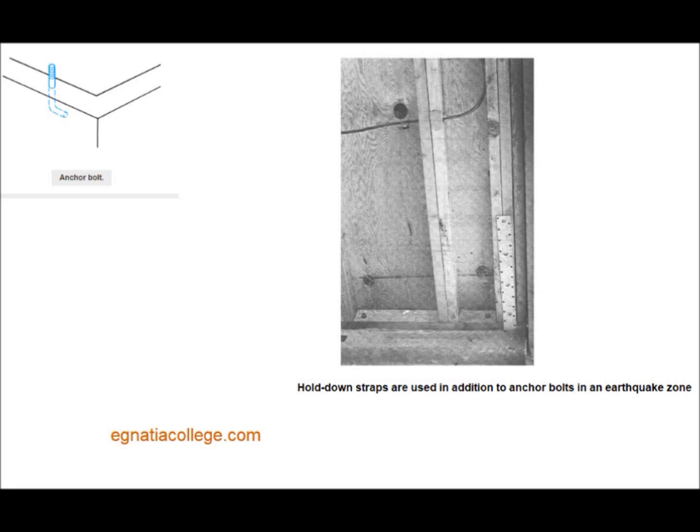They are held in place by filling the core with mortar grout. Grout is a Portland cement mixture that has high strength. In areas where there is a threat of extremely high winds or earthquakes, additional hold-down straps may be called for. These hold-downs are normally used only with concrete foundations.